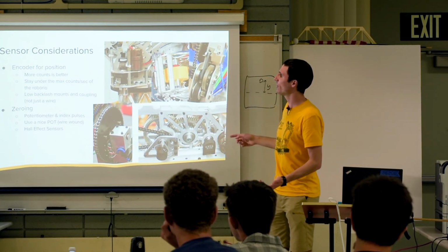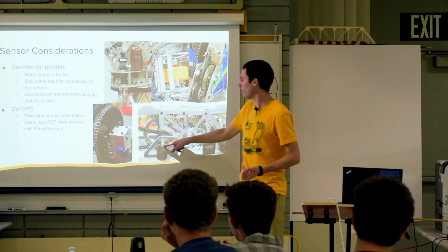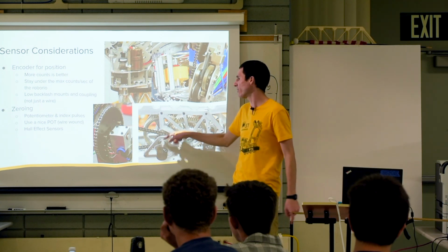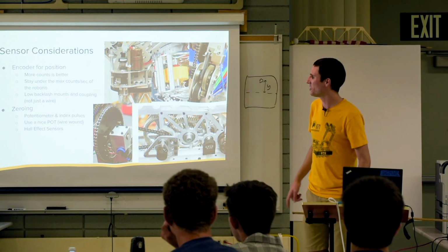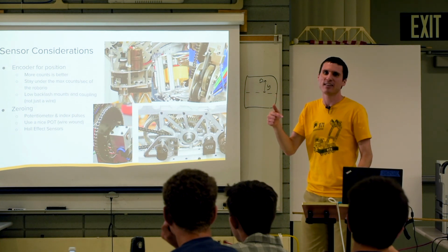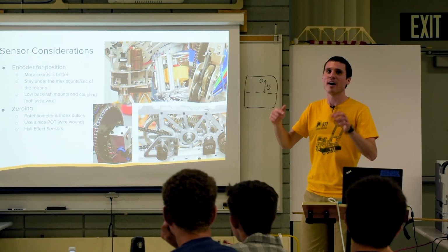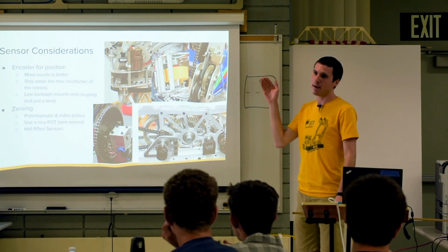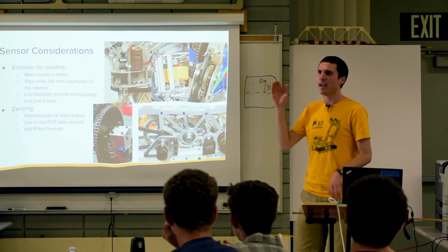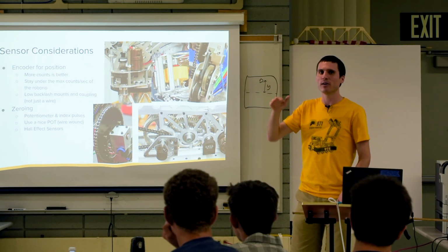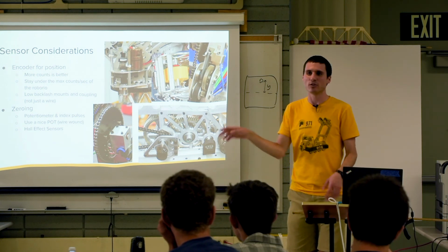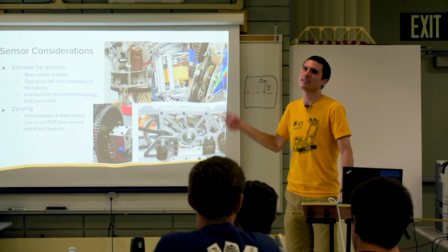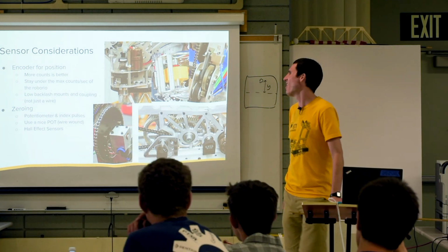And then another thing is you need to make sure that you have good coupling between the shaft on the output of the sensor and the shaft that you're driving. So in our 2013 robot, we just pressed the sensor into the end of the shaft and said, it's a close enough fit, it'll be fine. We ended up having a really frustrated evening where we were trying to figure out why the shooter kept missing. We'd drive around for a while, and it would slowly start shooting lower and lower and lower. We'd re-zero the system, and then we'd drive and it would shoot fine again. And we're like, well, what's going on? We finally traced it down to our encoder slipping inside of our mount. That was bad, our encoders.